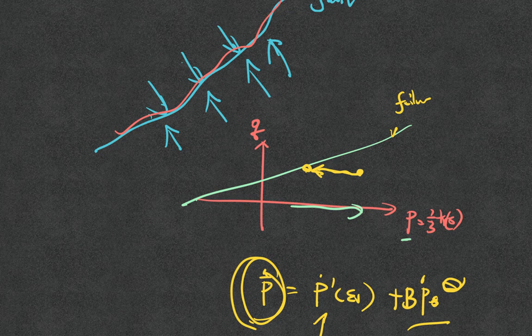Okay. So in the actual hydraulic fracture operation, you have a traffic light system. You're monitoring the pressure until it becomes dangerous, and then you stop. Okay, does that make sense? So that B becomes very important because you know at what point you need to stop the operations.